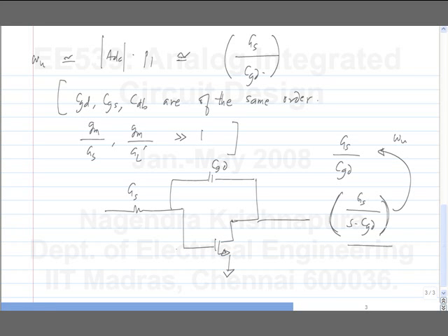What is the definition of the ideal op-amp? Yeah, so the input node has very little incremental voltage. That is, this is incrementally grounded. So this means that the current will be Vi times Gs and all of it flows through CGD. That's the action of the op-amp.